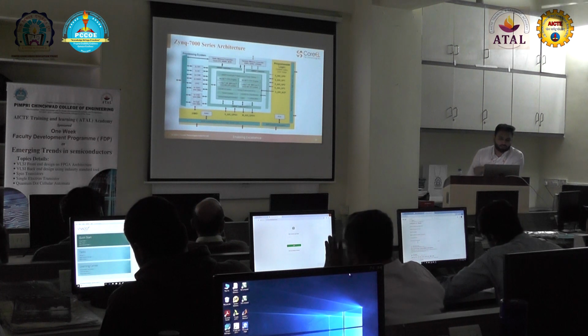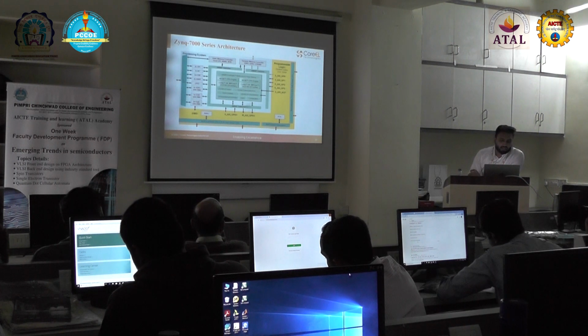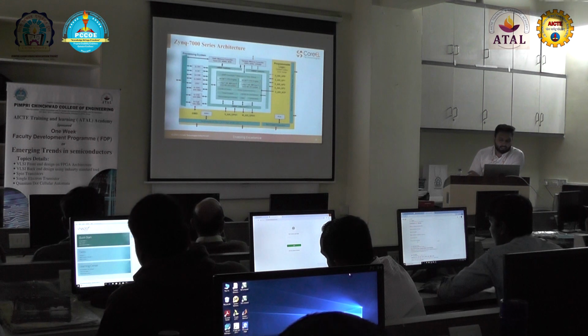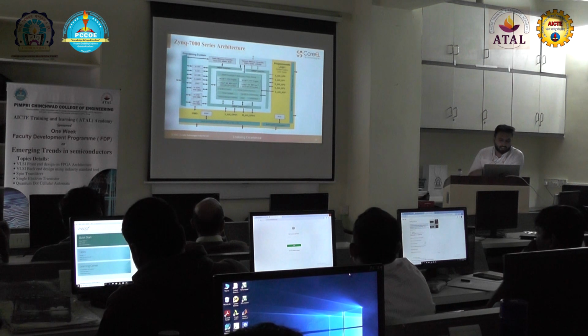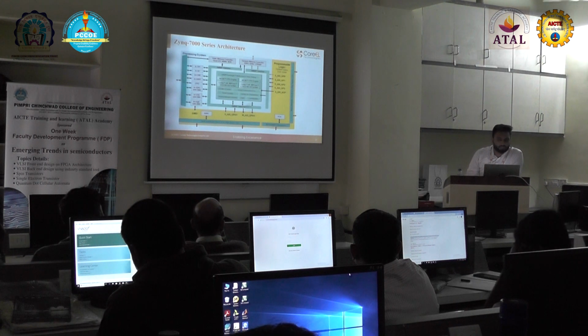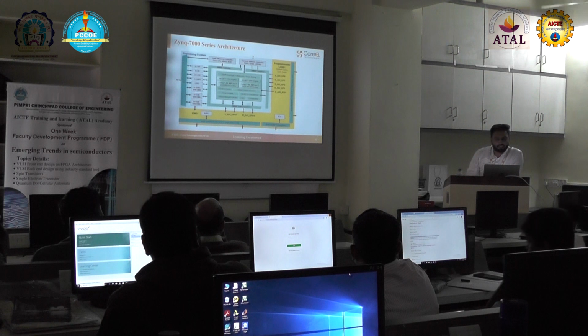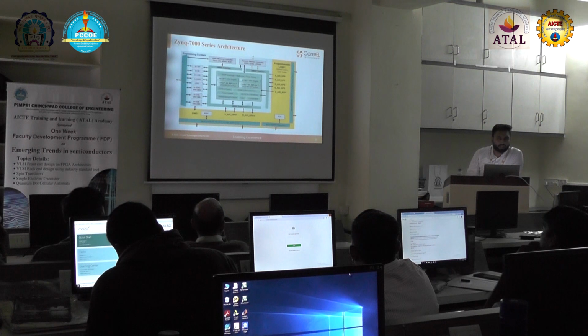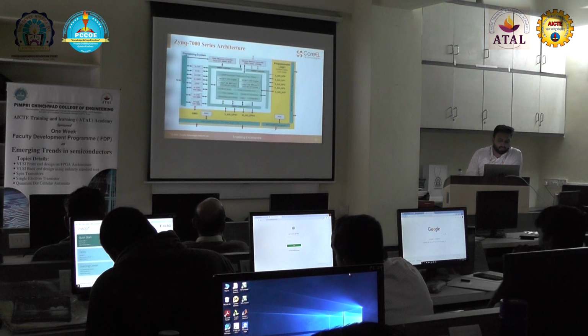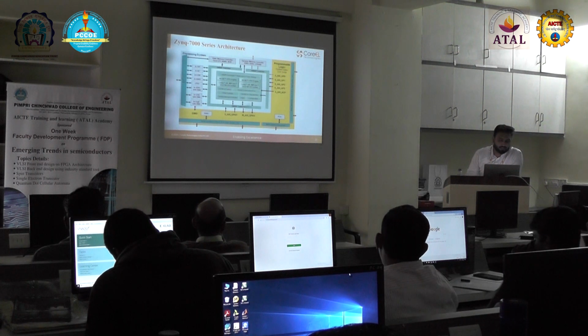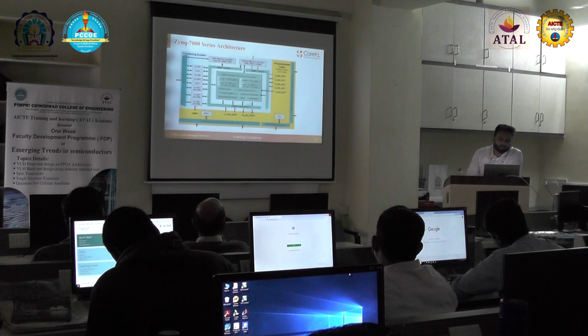And in the Cortex-A9 MPCore, it has an instruction cache and a data cache, each of 32 KB. The instruction cache is responsible for giving instructions to the ARM Cortex, and the data cache is responsible for storing data and streaming the Cortex-A9 processor's data. And here we have the L2 cache, which is 512 KB, where it stores only the necessary Cortex-A9 data.